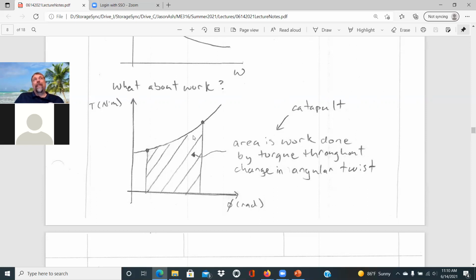Some of the things that were being noticed again was the longer arm, longer distances. Also, a lot of the arms were being broken when it hit the cross member. And through that dynamic analysis, I found that about 30% of the energy was going into actual energy to launch the projectile. We were using a tennis ball, and about 60%, a little bit more, was going into just stopping the arm from moving. So that's why a lot of the cross members were breaking.